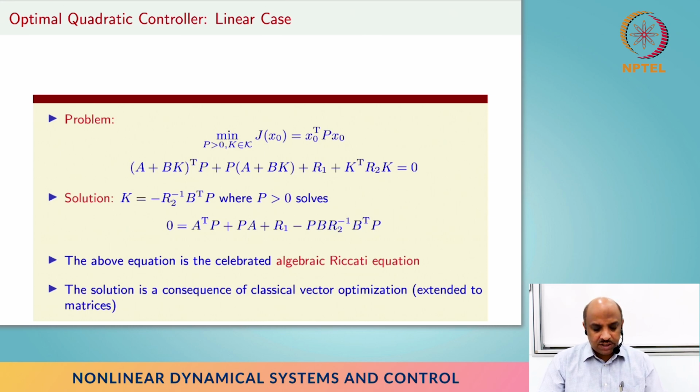So we have all these nice aspects to this particular problem, and once we substitute this K in this particular equation, then we end up with this algebraic Riccati equation, and this is really a celebrated equation. This is so-called linear quadratic regulator, and like I've said earlier, basically this also generalizes when we have actually noise and things like that, and that's equivalent to solving some H2 norm of linear system, right? So, but you get the idea.